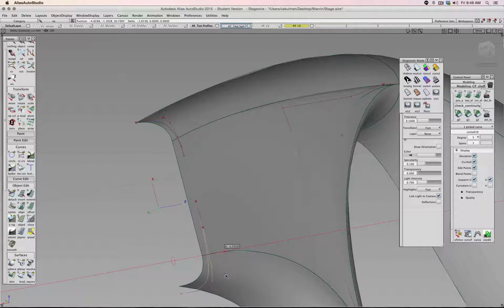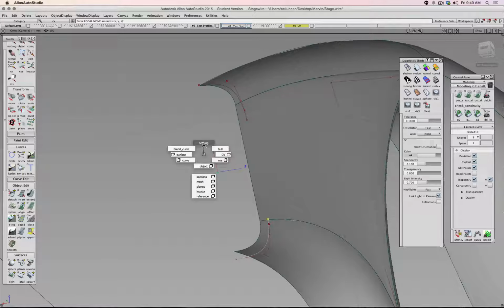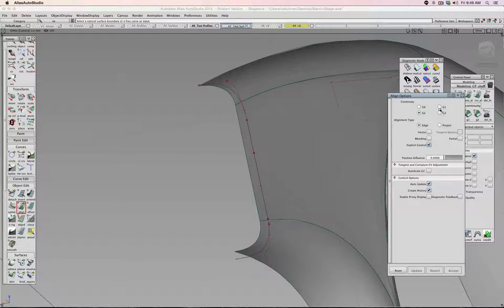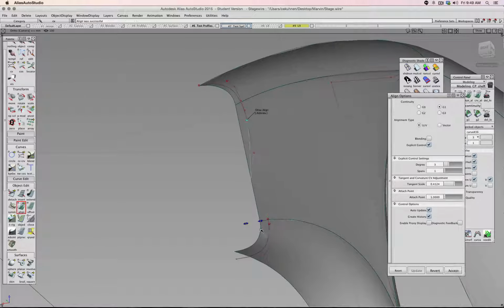Push those down, down, and I try to sculpt a nice transition. And then to get kind of like this line, later what I simply did was I put in a simple degree 2 line. Actually, no, maybe a simple degree 3, 2 points, accept, and then align tangent, this one to there, this one to there.